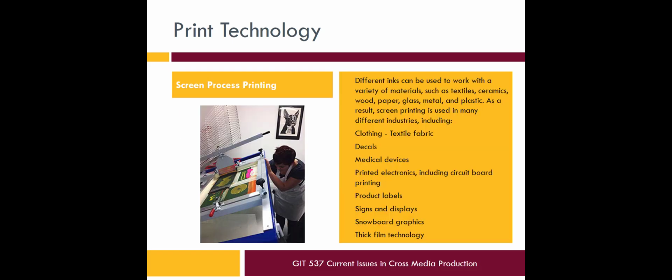Screen printing is a technique that's been around for quite a while. As the name suggests, this process involves pressing ink through a fine mesh or a screen to reproduce an image or design. Screen printing isn't typically a very fast process and is suited to smaller runs, and it works well also on non-standard items like t-shirts or skateboards and things like that.